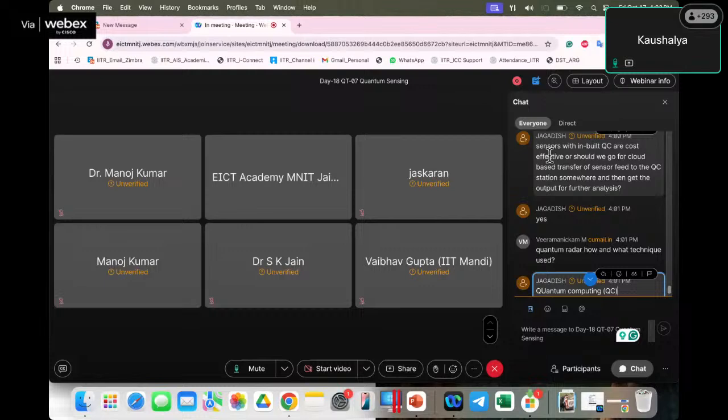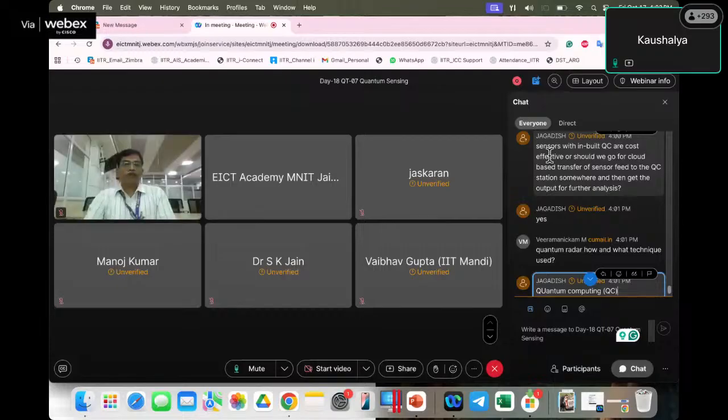That is something that many companies and many people at research level are also working on. If I speak particularly for the silicon case, there is a company based out of Canada called Photonic Inc. They have a prototype to have in one assembly the quantum emitter aspect. The silicon chip will sit there, and then the SNSPD is the detector part, and in between your waveguides, photonic cavities, and optical switches. They will come as a full package, a single system, and that is definitely much needed.